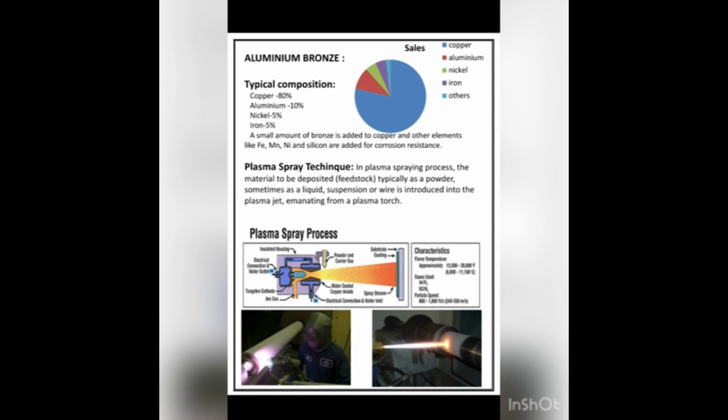Plasma spray technique. It is basically a spraying of molten or heat softened material onto a surface to provide a coating. Here, the material in form of powder is injected into a very high temperature plasma flame where it is rapidly heated and accelerated to a high velocity. The hot material impacts on the substrate surface and rapidly cools, forming a coating.